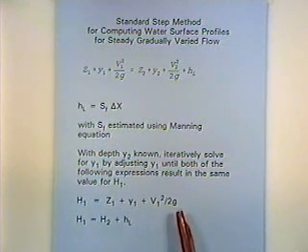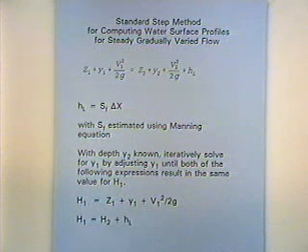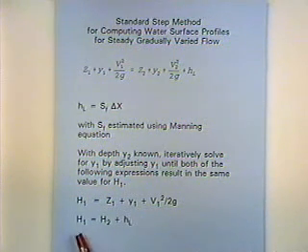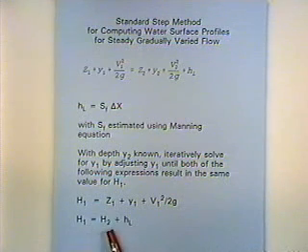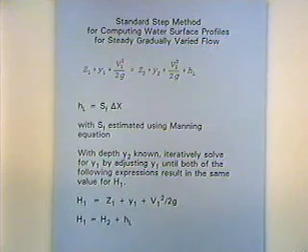That's a good equation. It's got to hold true for whatever y we assume. And also, the head at the upstream section is equal to the head at the downstream section plus the head loss in between. So both of those expressions are true. And so we've got to set up an algorithm to do that.